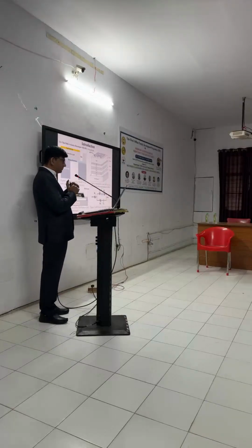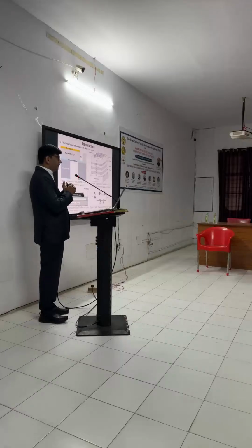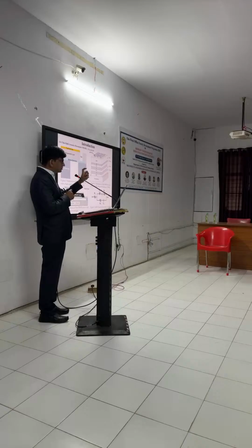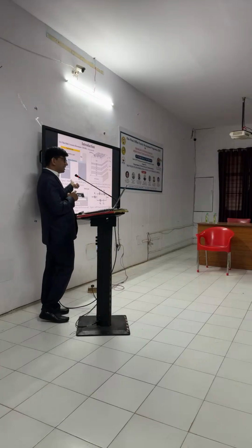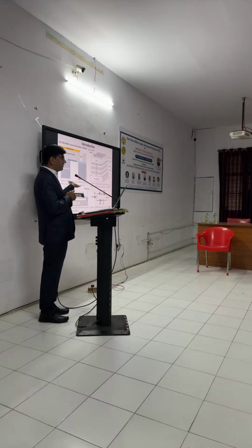Yes, that frequency depends on the confinement of the signal. But actually, how will this resonant frequency value be decided? That value depends on the thickness of the substrate, because Fr is given by V divided by twice of T. So V is the acoustic velocity of my substrate and T is the thickness of my substrate. But here the acoustic velocity is fixed for quartz, because we can't change that. What we can change is the thickness of my substrate. Okay, so the only thing in our hand is the substrate thickness. So now we have another device, the thin film bulk acoustic resonator.